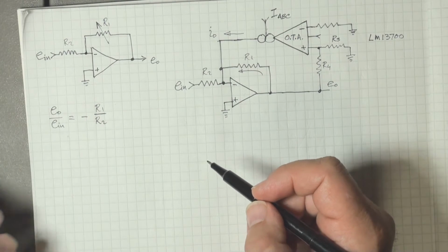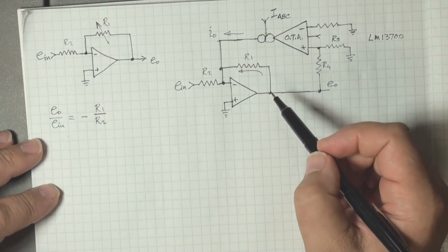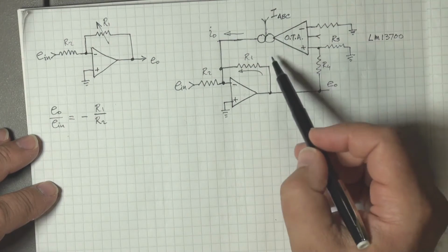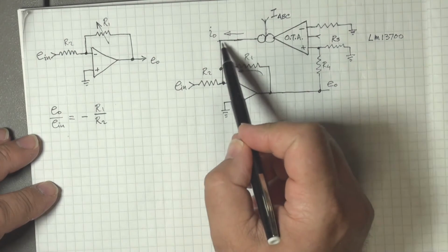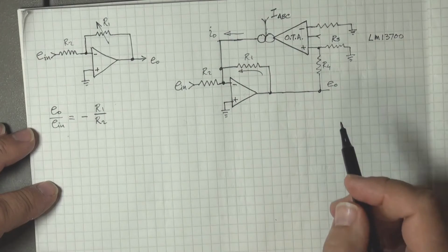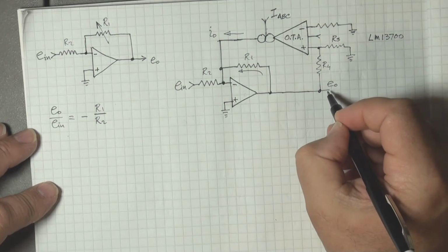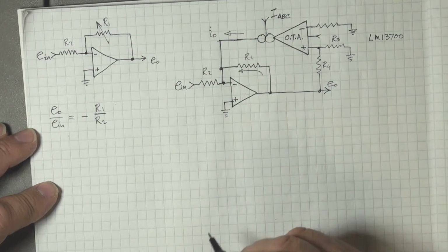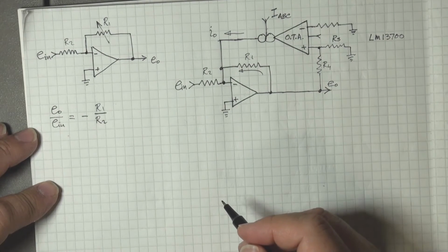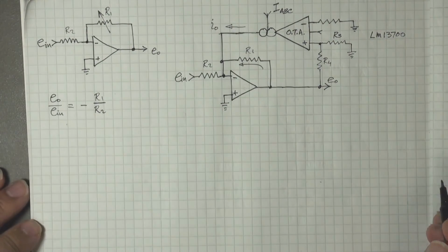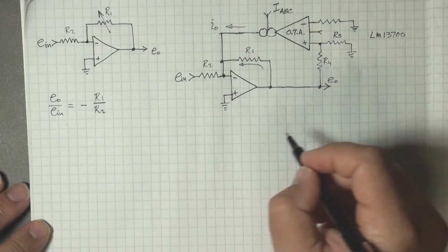So now, how do we want to control the amplifier bias current? How do we want to control the gain of this branch here? Well, what we want to do is sample the output signal of the op-amp and feed it into something called a peak detector.